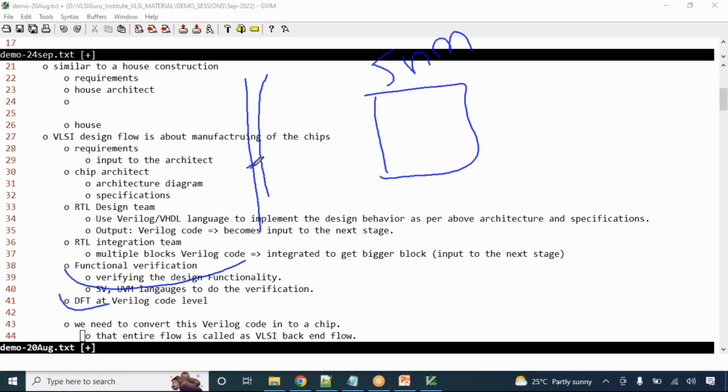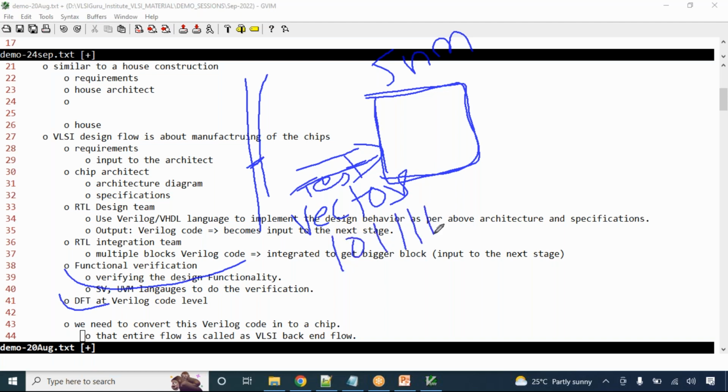How do you detect that this has happened? What they do is they take a chip, they apply some inputs called vectors. More specifically, they are called test vectors. You are testing the chip, and why it's called a vector is that there is a series of 1 0 1 1 1.